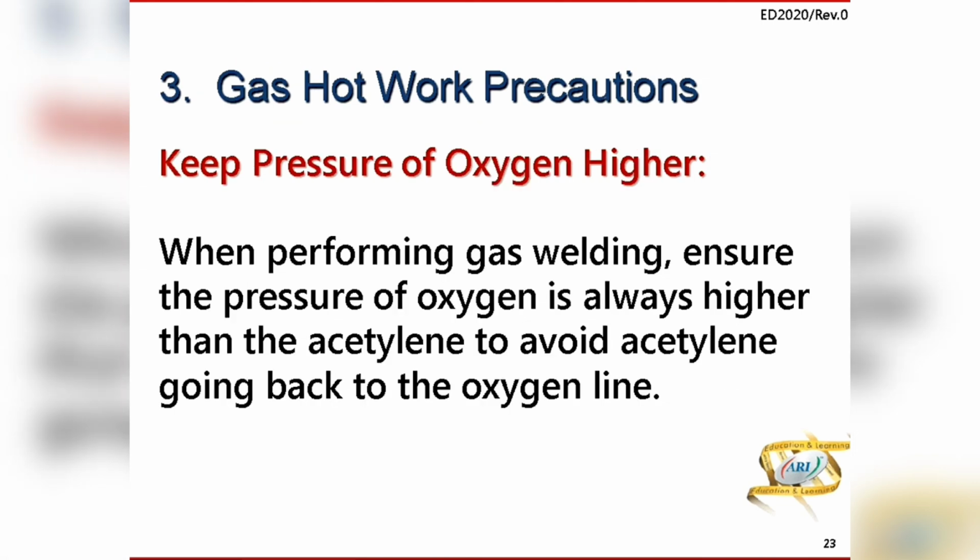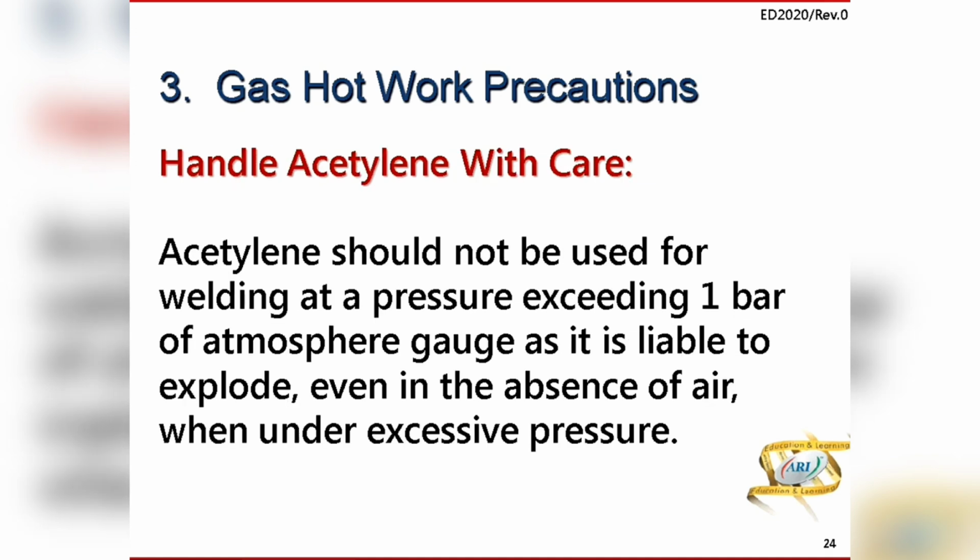So keep the pressure of oxygen higher when performing gas welding, and that should be higher than acetylene to avoid acetylene gas going back in oxygen line. So handle the acetylene with care. It should not be used for welding at a pressure exceeding 1 bar of atmospheric gauge, as it is liable to explode even in absence of air when under excessive pressure.